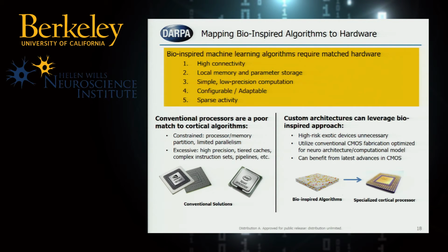I think the jury is out on whether spiking models themselves provide more capabilities to the algorithm, but I do believe that spiking models provide some significant optimization at the hardware level, in terms of needing only to activate a connection when a spike arrives and only having to compute updates to a neuron state when spikes arrive, and could provide significant power savings. We've seen some of that in the TrueNorth chip that IBM has developed and is now getting applications ported to.